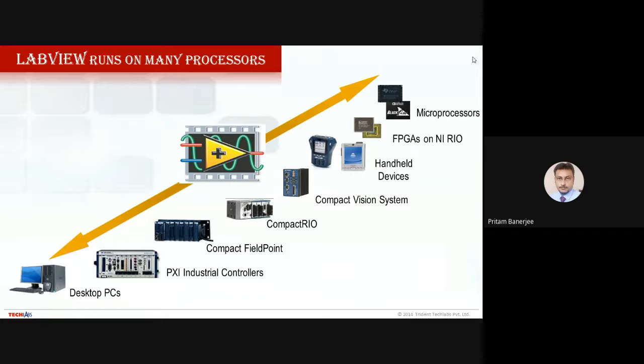And LabVIEW software itself runs on many of the major platforms. On your desktop, it will definitely run, but it also runs on different data acquisition cards, so that it is a complete embedded data acquisition card. You don't need to connect it always with the computer. Automatically the LabVIEW software is running over there. You just simply connect the sensors to the port to acquire or to generate with the instrument. It will be generating the signals or acquiring the data.